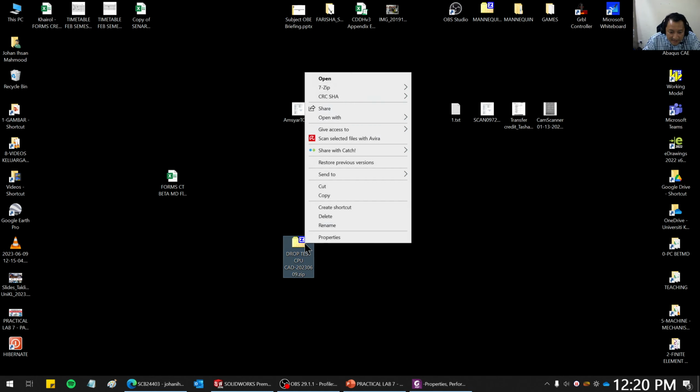And then we need to create one plane. In order to create the plane, I think I have to go to assembly and then reference geometry plane. I need some references. So I can choose this plane and this plane. I will automatically get a 45-degree angle. So this can be used for it to be dropped.